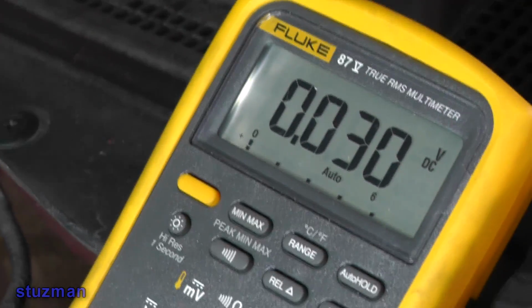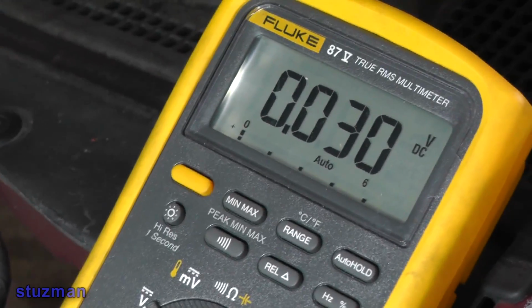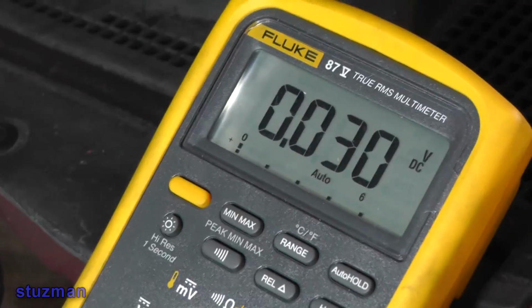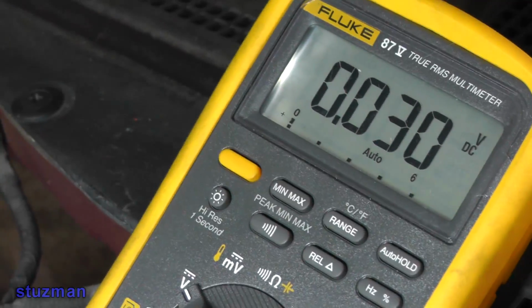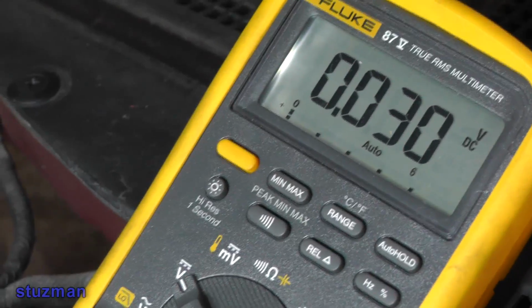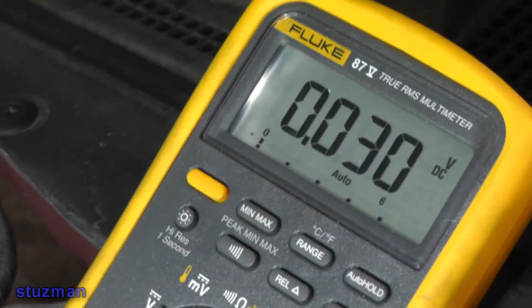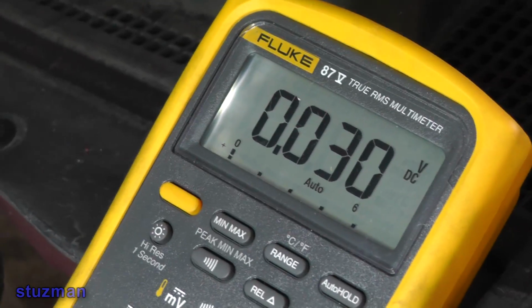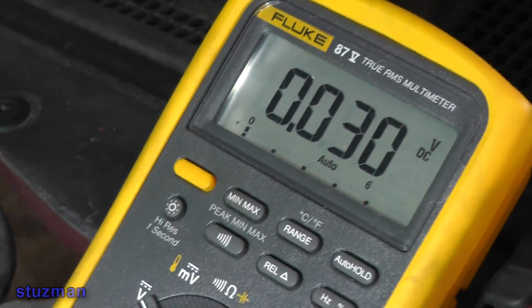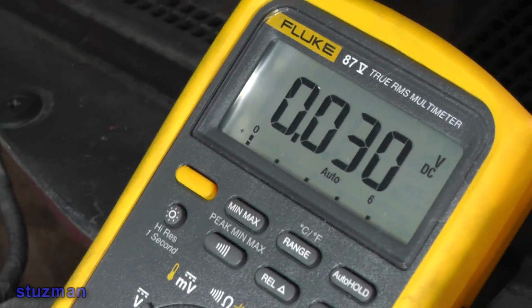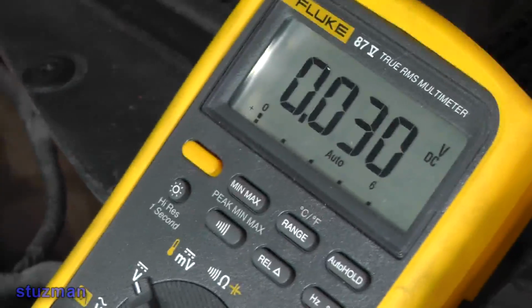But if you're looking and comparing relay contacts, this is the way you can do it. You're doing it dynamically under actual load conditions. It's a lot better doing it this way than putting an ohm meter on there, pushing maybe like 20 milliamps of current through there. That's not simulating a load. You've got burnt contacts and things of that, oxidation. You close the contacts and you're still probably going to get a good reading through an ohm meter.